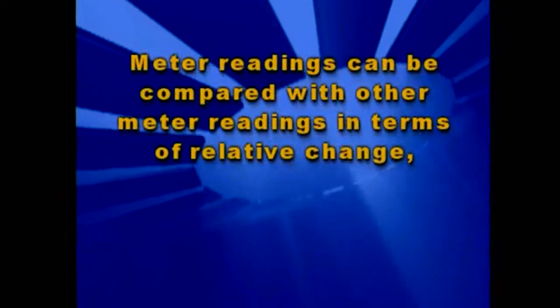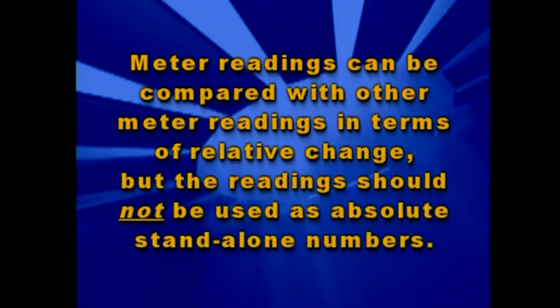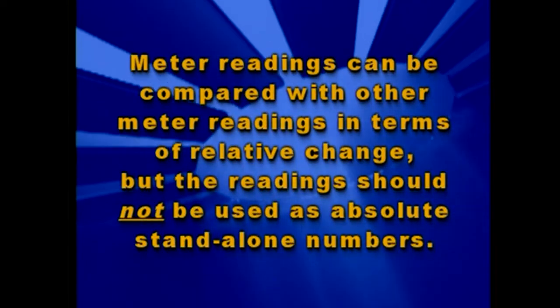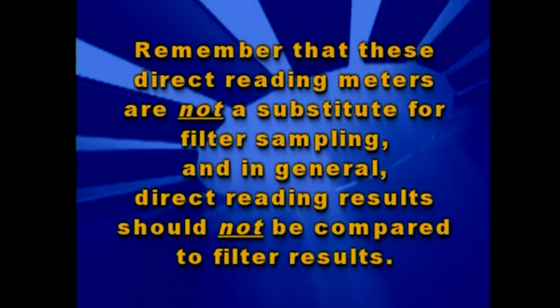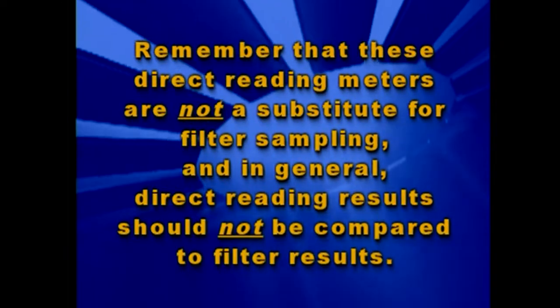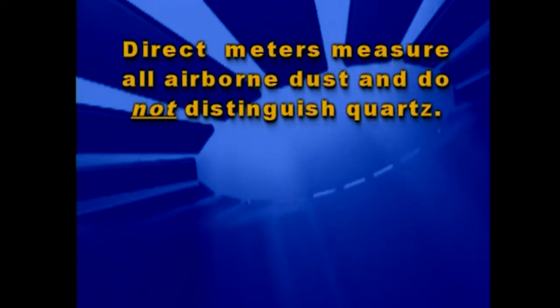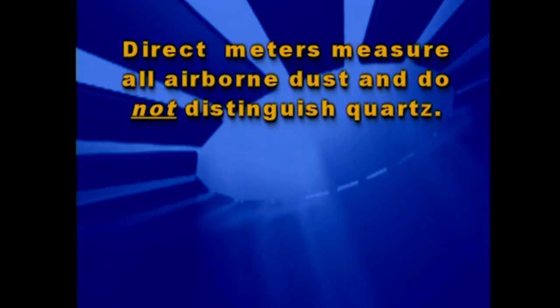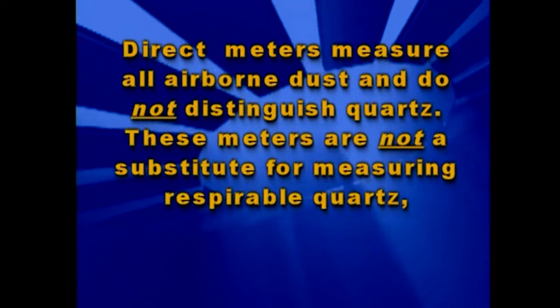Therefore, meter readings can be compared with other meter readings in terms of relative change, but the readings should not be used as absolute standalone numbers. Also remember that these direct reading meters are not a substitute for filter sampling, and in general, direct reading results should not be compared to filter results. Again, this is because the direct meters measure all airborne dust and do not distinguish quartz. These meters are not a substitute for measuring respirable quartz, but they can be a valuable addition.